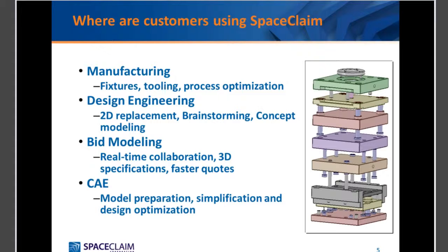Now, people today are using SpaceClaim for a number of different things. We have manufacturing people that are using it to make fixtures and tooling, designing and concepting from scratch, and also using it to simplify models for CAE. We're going to be mainly talking about SpaceClaim for injection molding today, how we can prepare it for MoldFlow or another mold package, how we can make a core and cavity for the actual mold assembly, and also how we can make edits to the plastic part so it's more idealized for the eventual mold assembly.